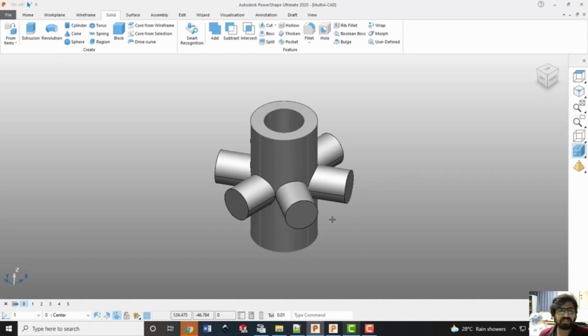But in this case, it is clearly visible that the center portion, which is right now highlighted in orange color, can be easily fabricated on a 3-axis machine because it doesn't have any overhanging feature. But these features, those are on the periphery, will definitely require some support. So let us first build this center part, which is easily manufacturable on a DED machine without any support structure.